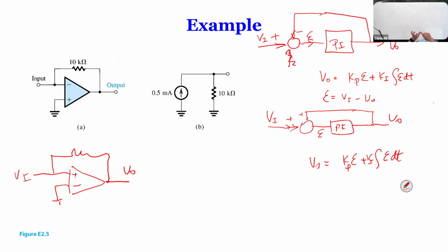If your input changes 20%, your output changes 20%. Translated to a phone, your input signal comes in at 1 millivolt and you can hear clearly, but if it changes 20%, you cannot hear anymore because it's too low. But with feedback control, if your input changes 20%, your output only changes maybe 1%. So it stabilizes your output. Very useful.